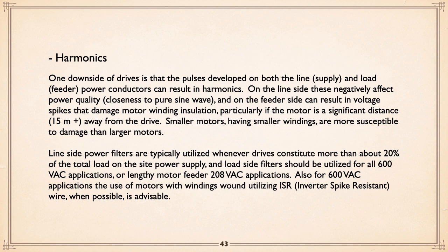It's been quite a significant thing. Now let's look at a couple of disadvantages. One thing with the drives, because of the pulsing on both sides, even the rectifying, it creates pulses. You can get harmonics on both the line and the load. On the line side, it affects power quality, how good a sine wave it is.